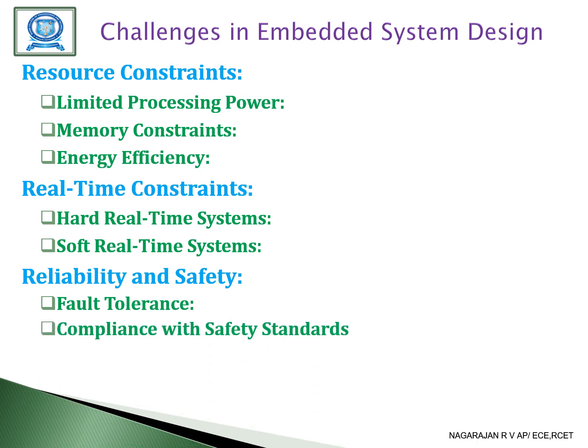And next is compliance with safety standards. Many embedded systems are subject to industry specific safety standards such as ISO 26262 for automotive safety or IEC 60601 for medical devices. Compliance involves rigorous testing, validation, and documentation to ensure that the system meets safety requirements and can be certified for use.